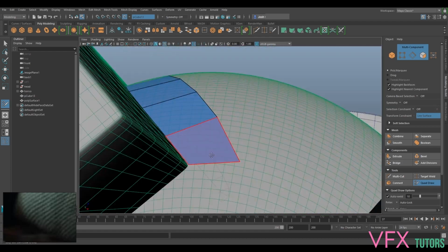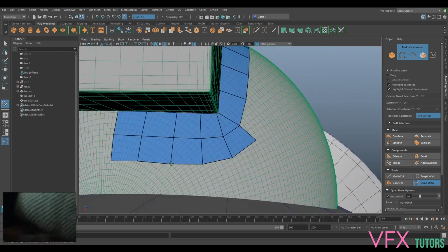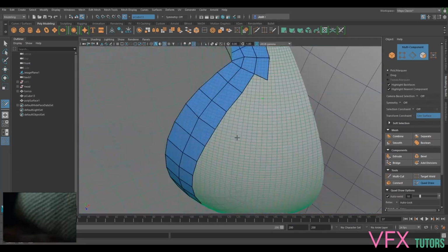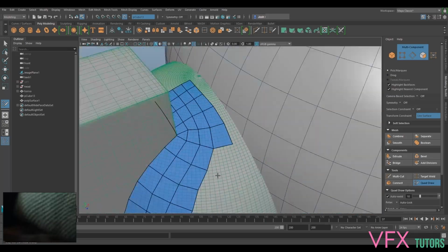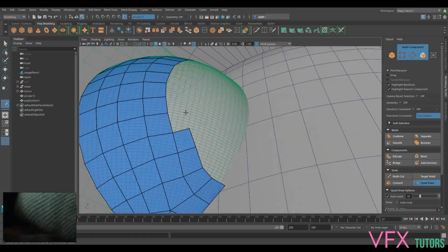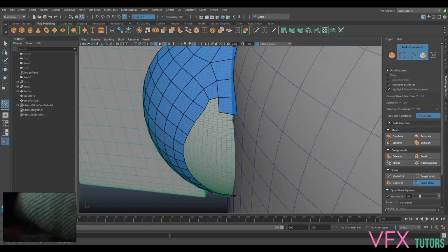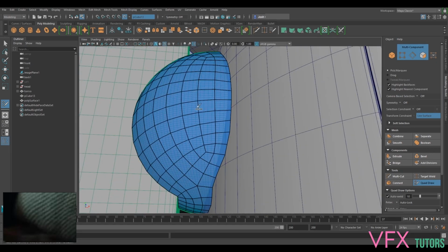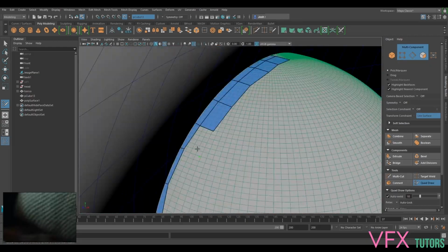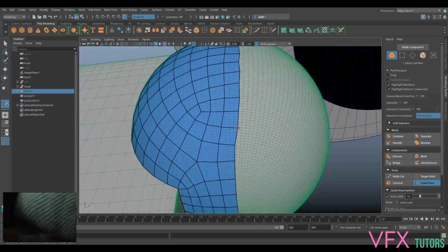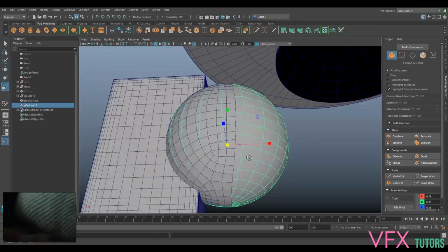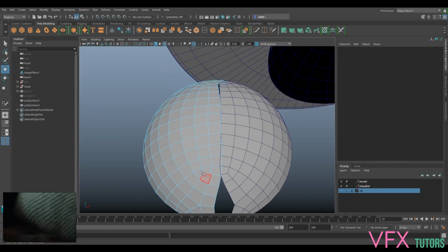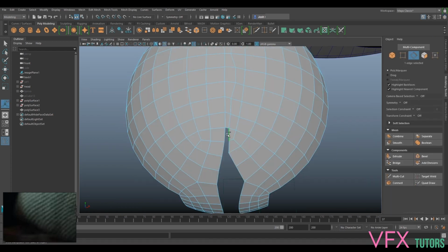And this is another example of the quad draw technique that I use quite a lot. That's not a super complicated shape, but I want to make sure that it's subdivision friendly, just in case. They're not really ever going to sculpt this, but it's worth going through the motions anyway. So you can see that I've made a high res base mesh, smooth, and just use quad draw over the top, so I can focus just on the topology and not have to worry about the shape.